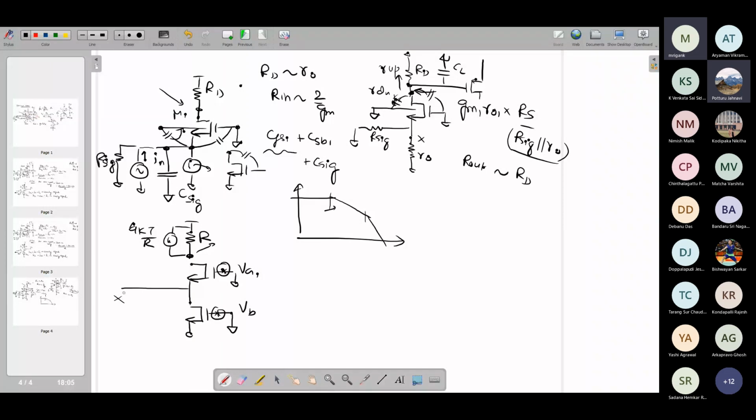So in this case, which of these two transistors will contribute to the output noise more? Sorry? The lower one has higher gain because it's common source. Yeah, so this is a common source kind of device, right? Because the source is shorted to ground, whereas this one is a cascode device for this noise analysis. So for noise analysis, this is like a common source, which is going to directly contribute to the output noise.